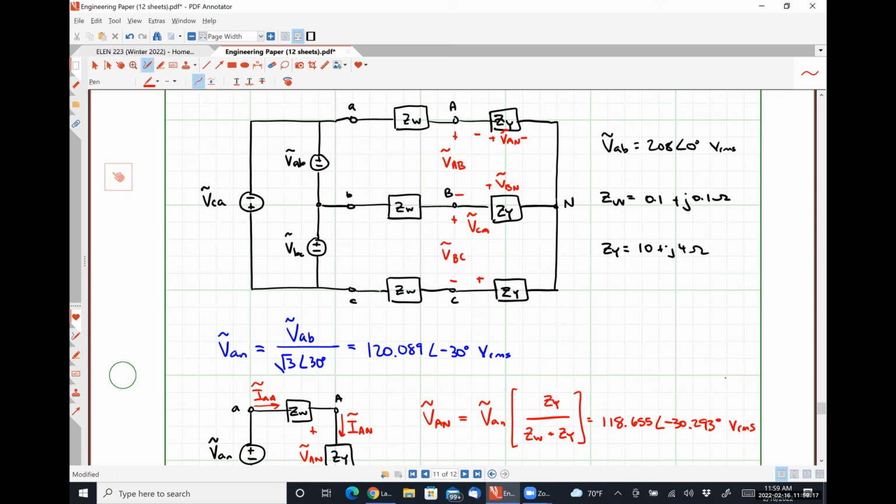We were given the phase voltage at the source, and for a delta connection, that is the same thing as the line voltages at the source. So there's no work involved there literally at all. What about our phase currents in our source?